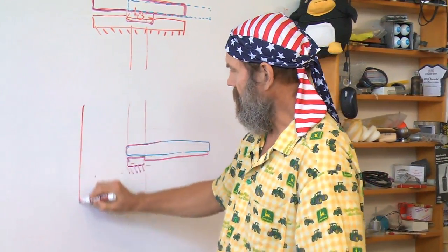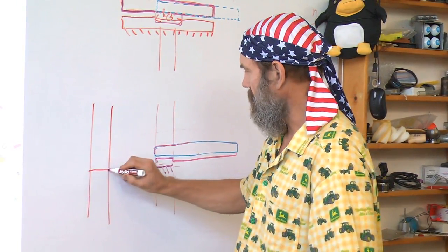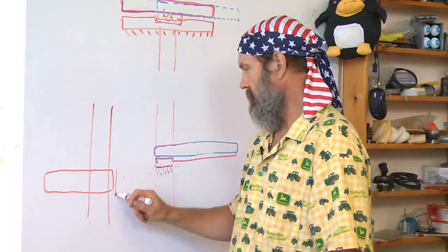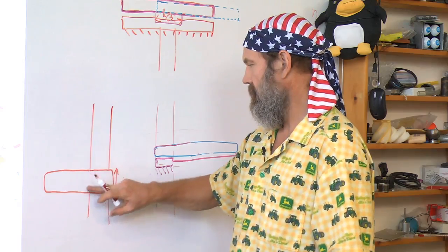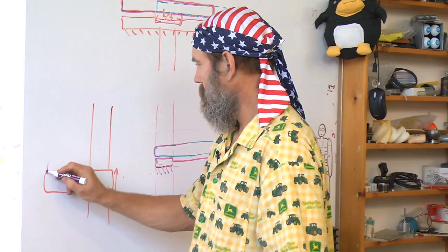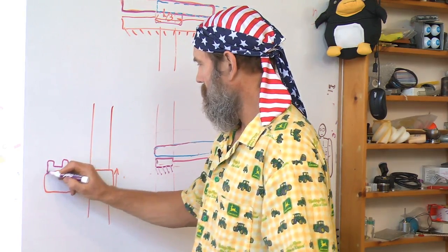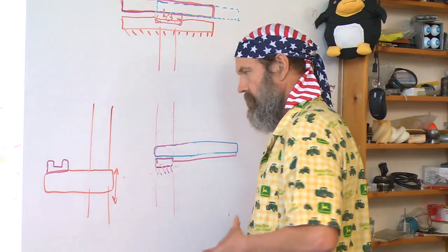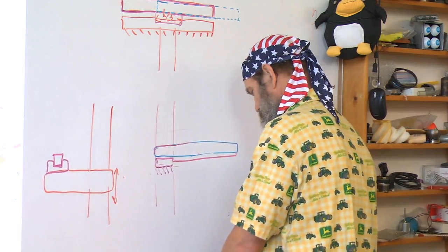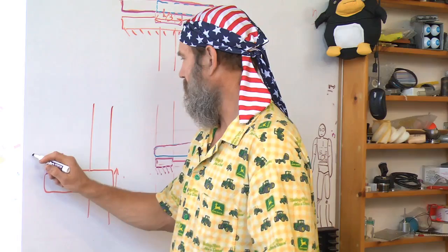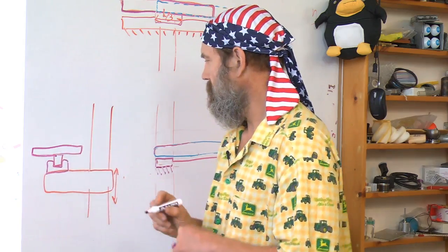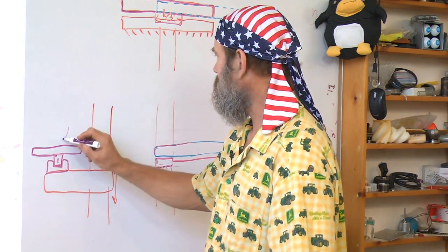So if I look at the side view, it's implying to me that here is this column where this goes up and down, and I have the bearing block. Here's the bearing rail and the table attached to it. So this moves in and out of the board. This is my x-axis.